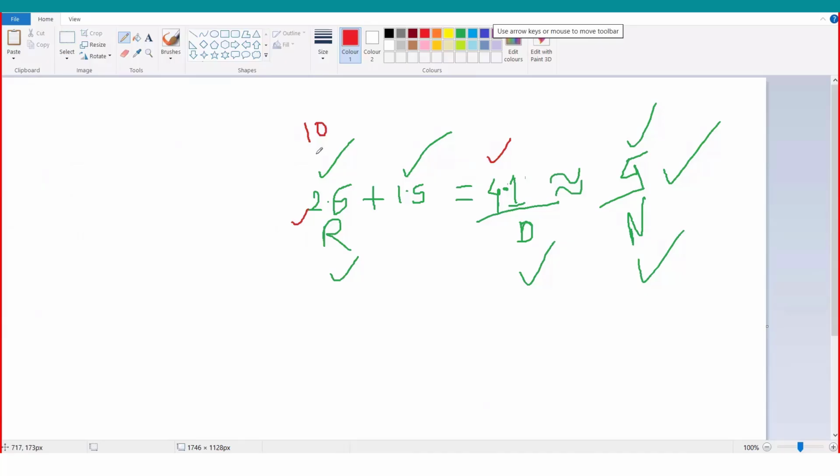It has not been used yet, and that's why it is new, and it is not in hot condition, it is in cold condition. So if I use 5 mm as the thickness and back calculate the pressure, let's say it is 18 bar, roughly, approximately. These are not the actual values, just for understanding purposes.